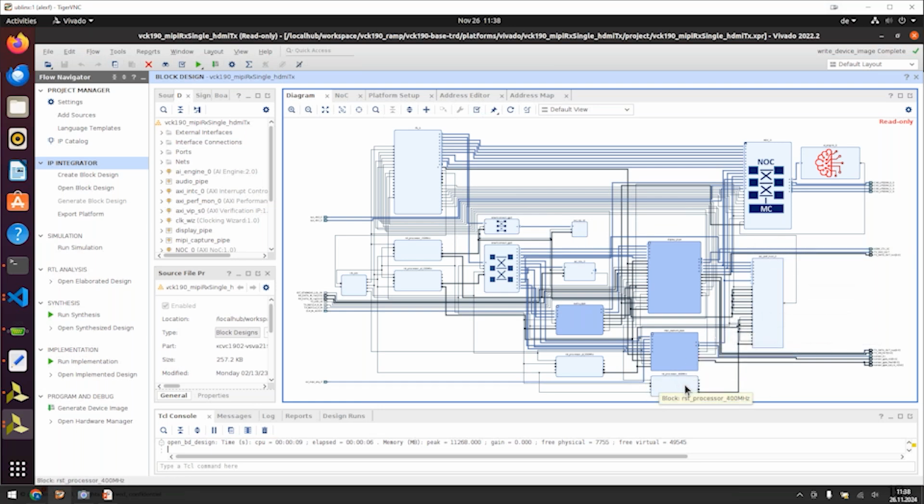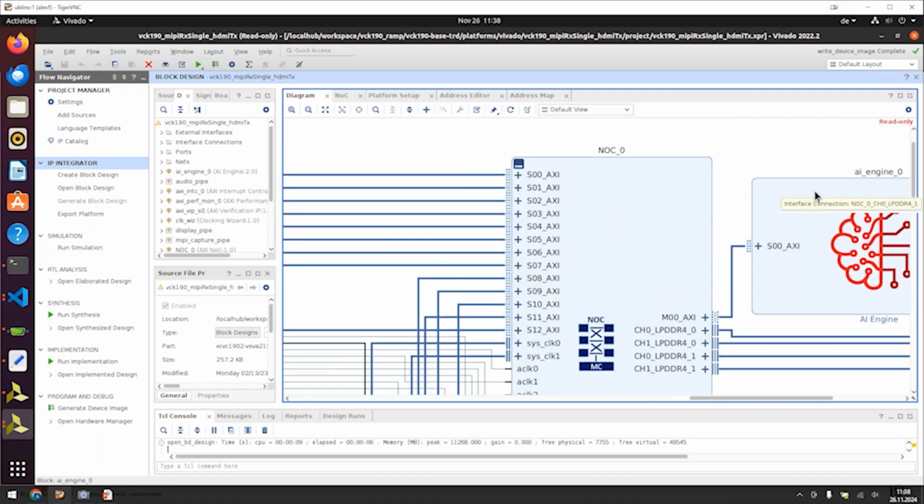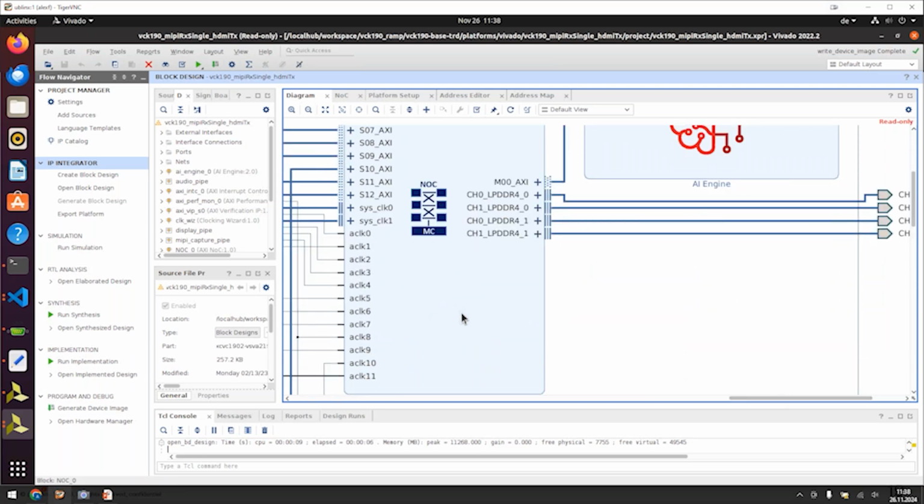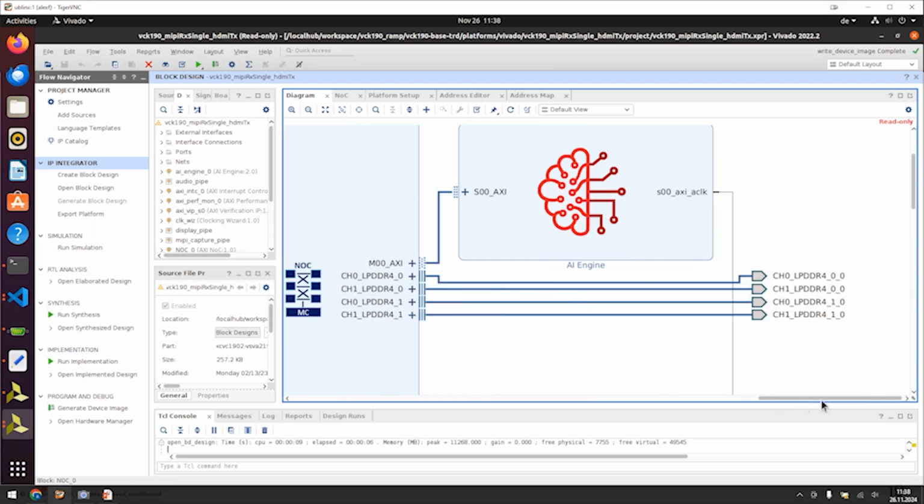So when you are checking out this repository, when you run the makefiles for the actual platform, you will get a Vivado project underneath it that I just opened and tried to show you. This is kind of specific for Versal, of course, because the AI Engines are not available in the other devices, and the NoC is not available in the other devices. But what you see here already is that the design is incorporating all of the DDR controllers in the device, and it's incorporating the AI Engine, at least addressable from a control port perspective. There are no functional ports in there.